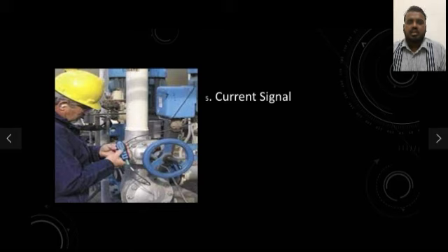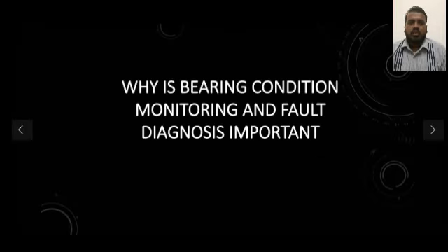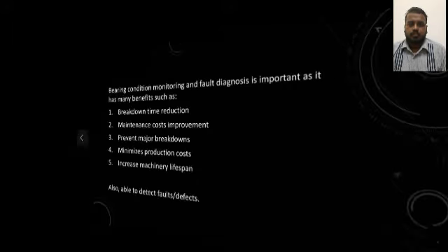Via the data collected through these 5 techniques, maintenance personnel can determine the faults, defects, lubrication level, and wear that are present on the rolling element bearing. This process is called fault diagnosis. Next, now let's look at why bearing condition monitoring and fault diagnosis is important.